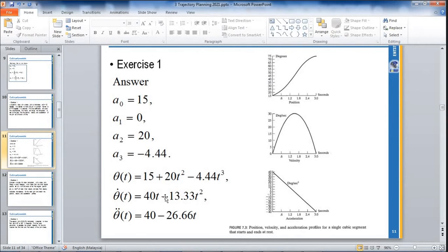If you didn't have this equation, your robot would have a lot of stoppages. So it's not smooth. If you reach your final point, your motor will drastically stop, so that's why it's not smooth. If you carry a soft material, it will break or maybe drop out because you stop your robotic arm immediately. If your arm is carrying any fragile product, the product will break.